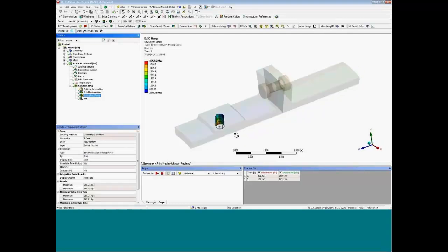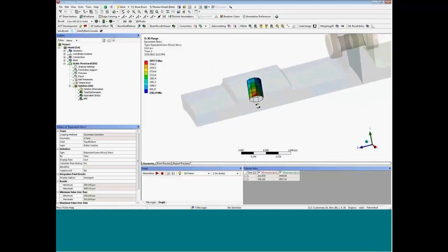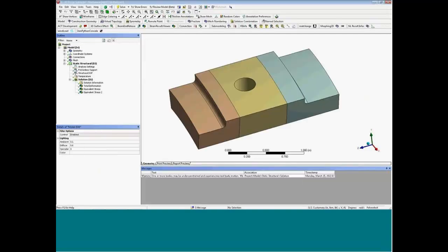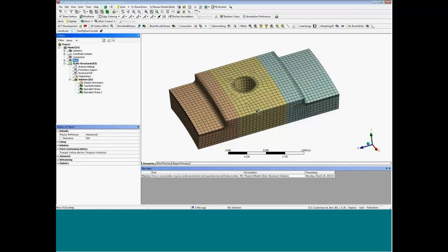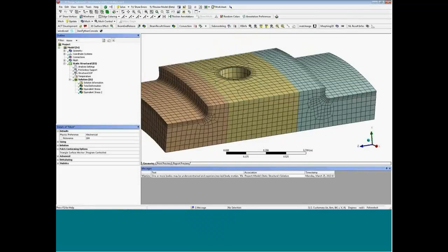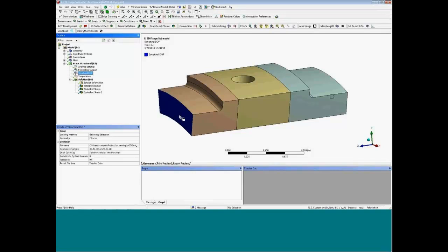So then let's say we also looked at stress. We find the stress in this hole at some value. And see that this is a fairly coarse mesh around there. So maybe we want to, without having to rerun this entire model, just submodel this local region in here. So then we can do that and use the submodeling extension for displacement. So we build a model of just this localized region. We have a much more refined mesh on here where we, you know, have some more elements near the surface. And then we apply this submodeling for displacement, degree of freedom mapping, and then click the 2 faces here.